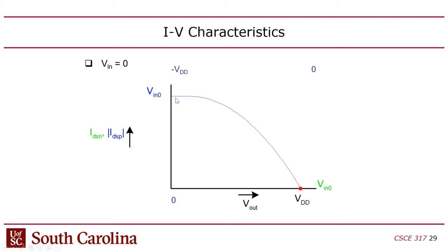So as you increase the voltage from negative VDD to 0, you start out in saturation mode, then you switch to linear mode, and then you basically go to nothing. And you don't go to nothing because you go to cutoff. You go to nothing because the voltage hits 0. So once the voltage is 0, the current is 0, even if you're not in cutoff mode. You can still be in linear mode and have zero current through this transistor. Okay, so we do that for 0. Let's see.